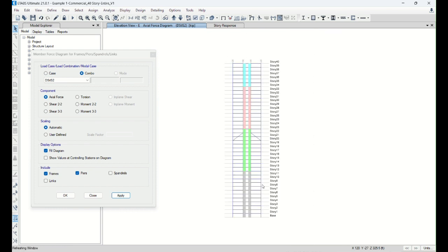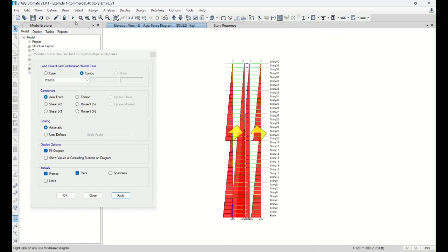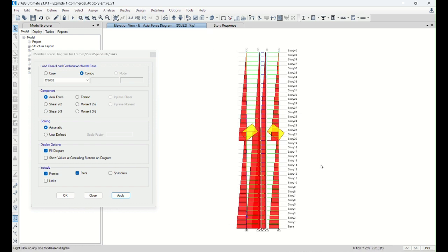Likely you're going to underestimate your gravity forces on the column side, in the column design. Previously, you designed the column based upon only gravity loads, but now since you tie the column with the core wall with an outrigger, these two columns, right, and the other side is not only a gravity column. This also works as a lateral column because it contributes. So we need to take the actual forces due to any lateral wind forces.